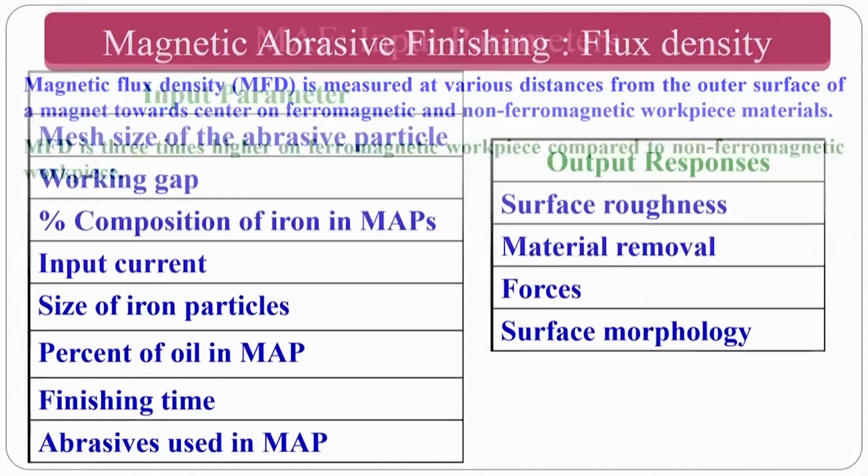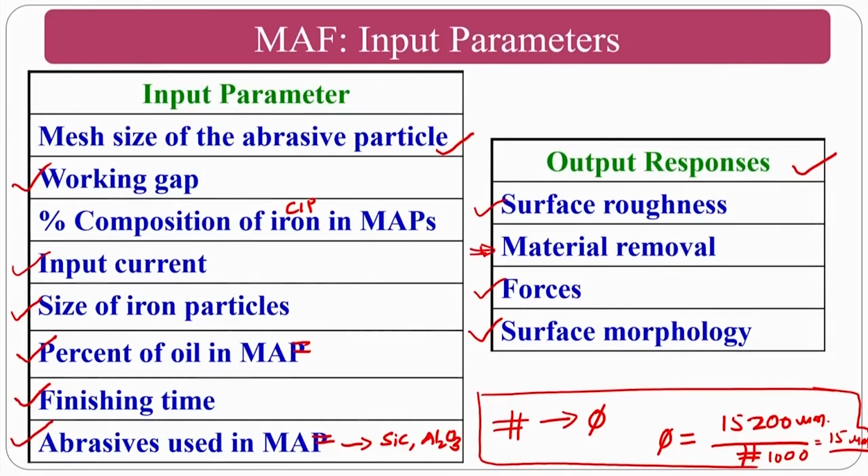That means surface morphology also plays a major role for your application. Application to application, the surface morphology changes. You cannot use the grinding morphology or the turning morphology for the engine cylinder. There you have to use the surface morphology of the honing process only.